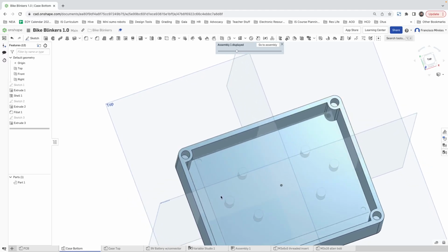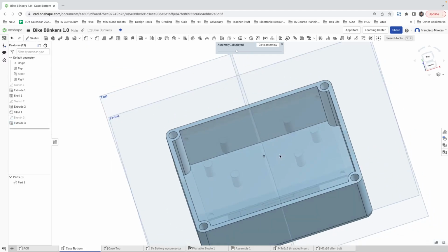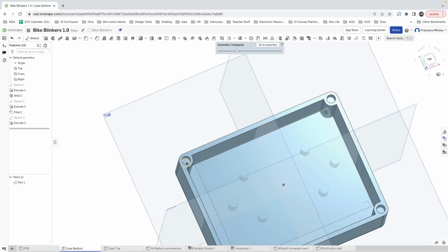You know what? I don't like it. Here's the issue, because yeah, that's an issue. All right. We should have 2 different diameters, yeah. All right. Like this should only be as deep as our threaded insert, so it should be 6. And then I should do another hole a bit smaller for just the remaining bolts.